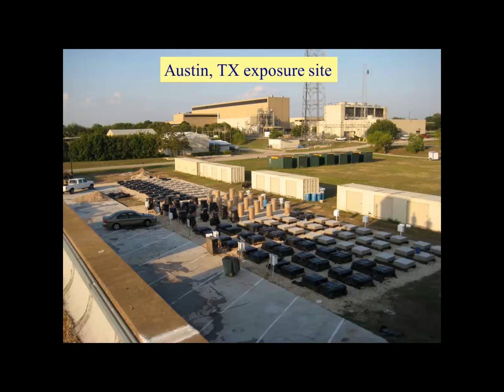Now, if that high-performance concrete included sufficient amounts of fly ash, slag, or silica fume, so that you're actually reducing the pH internally enough, then the HPC would be the answer for ASR. But let's say you had another high-performance concrete mix that in and of itself was not resistant to ASR. That concrete would last longer, but it eventually would fail as well.